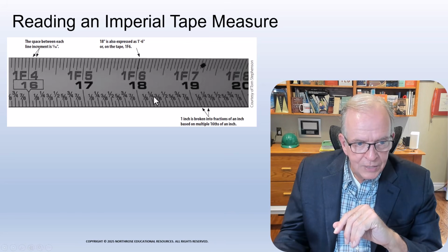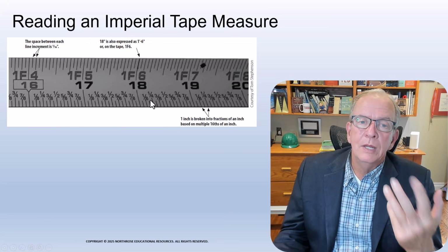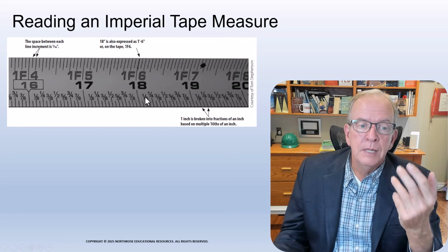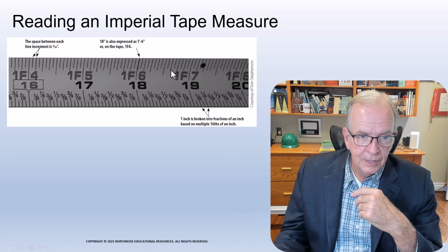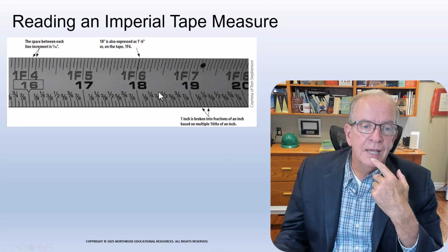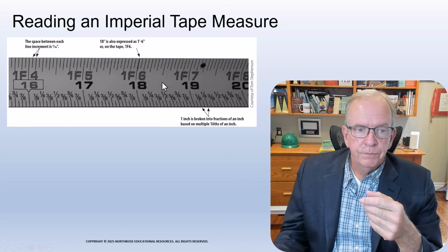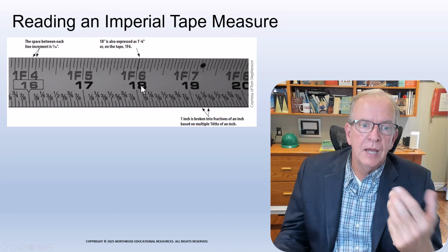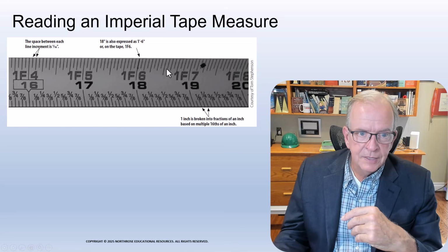This is showing in eighths, quarter, 3/8, half, 5/8. And that's usually, if I'm doing a measurement and I'm calling it out to another carpenter to cut something, I might say, I need a piece that's 18 and 5/8 long. If it's 18 and 5/8 long, I would go to that point there. Or I might say now 18 and 9/16. 18 and 9/16 will be right here because that's 8/16, that's 9/16.